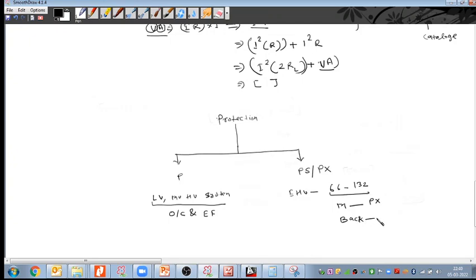For the backup protection we take the overcurrent protection and the earth fault protection. So for these protective relays, same as the medium and high voltage systems, we take the P class CT. So up to this voltage, we use both PX and P class CT cores: PX for the main protection and P for the backup protection.